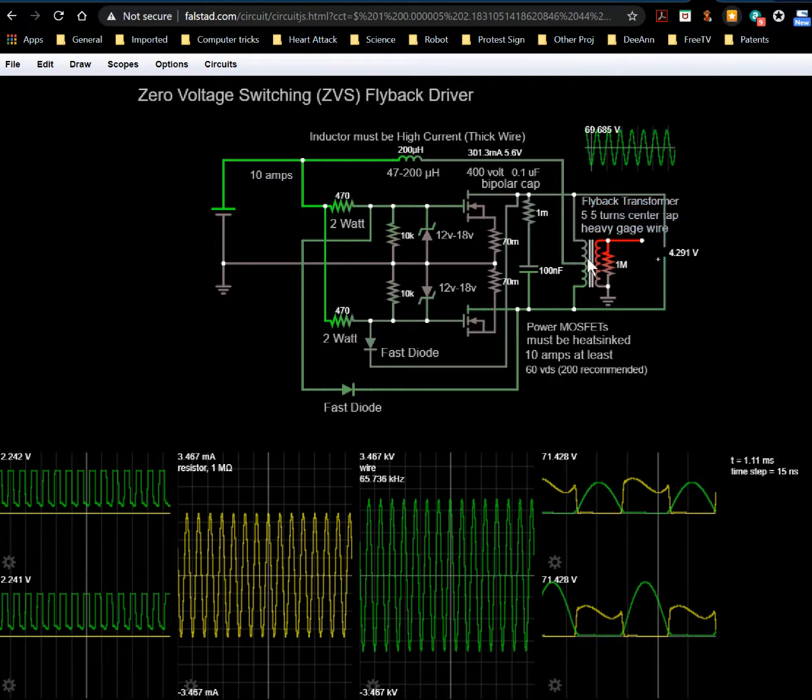near 0. Now the thing you have to keep in mind is this is a tank circuit, and because of this, we're actually measuring the voltage not just across the capacitor, but across the inductor too. Because in a tank circuit, the capacitor and inductor are in parallel. Because of that, the voltage across them will be in phase. But the current flowing through them will be 180 degrees out of phase. That's something to keep in mind. The important thing to remember is that the voltage is the same.